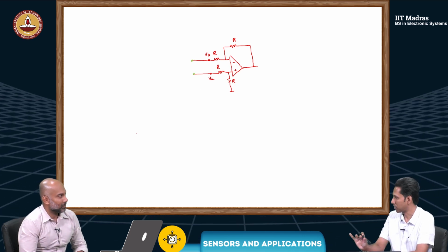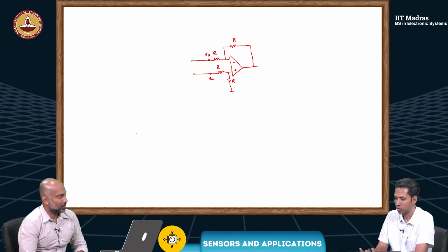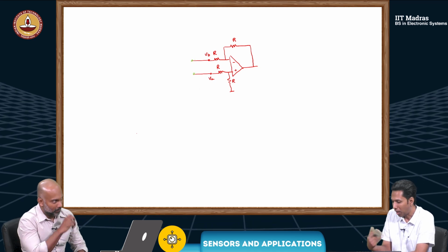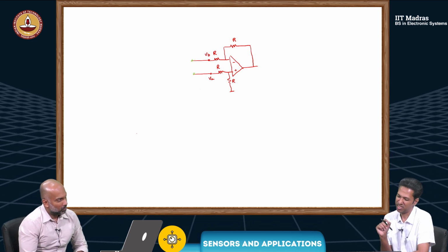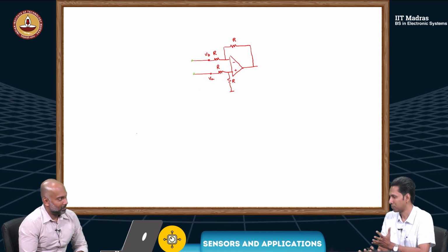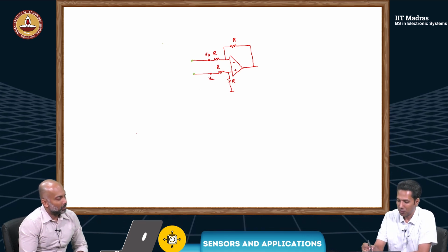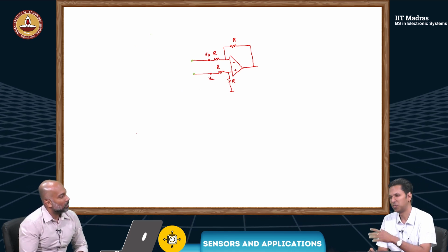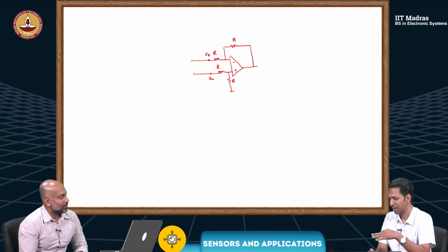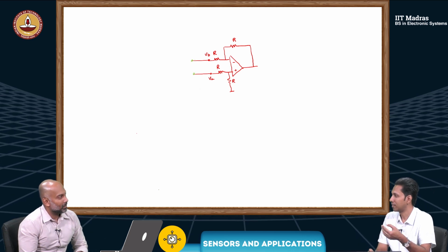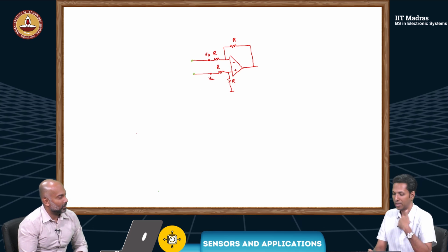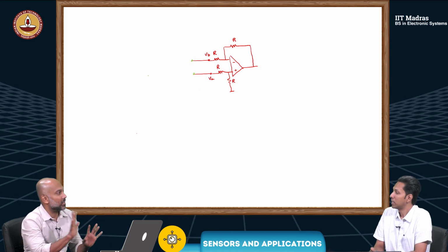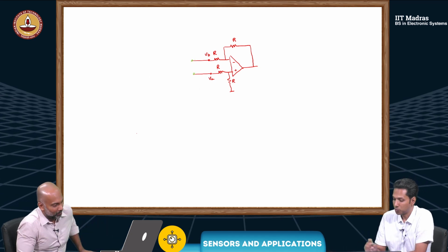So I get matched resistors, and then I get very good CMRR. I'll use that. Then for amplification, like I said earlier, I would like to change just one resistor alone, not all. So we will replace or modify the voltage follower circuit here with some scheme that can provide gain control. So you're not depending on the gain from these resistors? Yes.